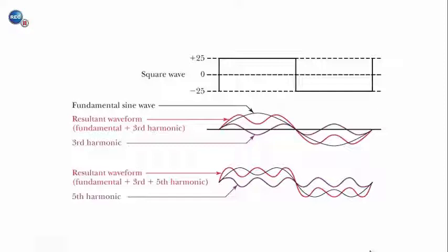And so here you can see that we have a sine wave with a fundamental frequency and a fundamental period. That's the longest period sine wave that you see here. Then we have a sine wave that is the third harmonic. What that means is that the period is 1/3 of that of the original wave. The original wave had a period of this entire time, and the third harmonic's frequency is 3 times that, right? So we get 3 oscillations of the third harmonic to only 1 oscillation of the fundamental sine wave.